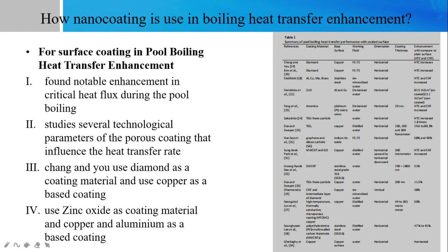The working fluid was water, and a concentration of aluminum oxide nanoparticles below 0.01% by volume was taken into account. The tests were carried out on the nanoparticle coated surface to improve boiling heat transfer.